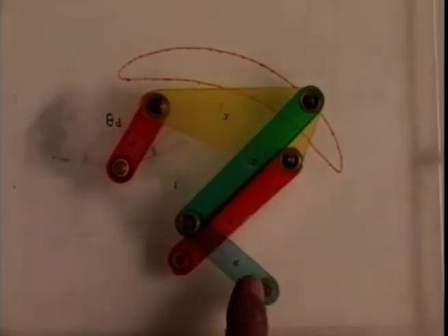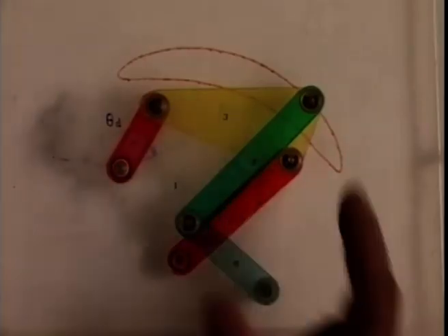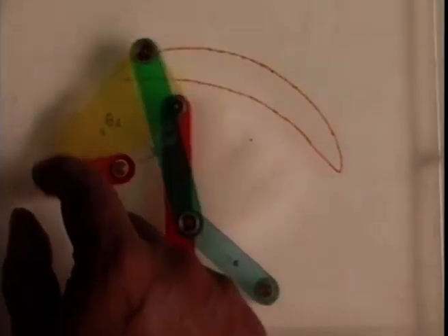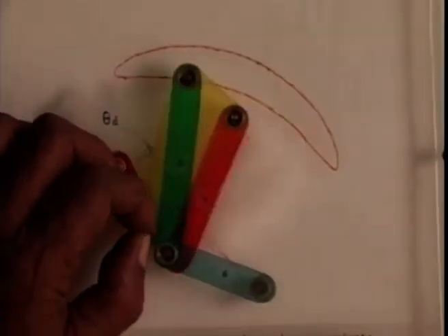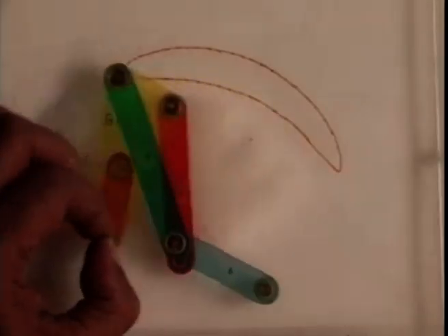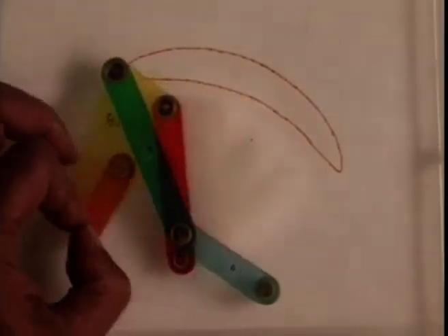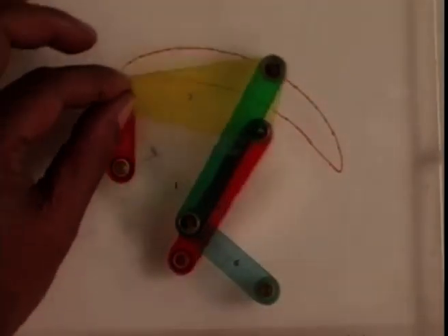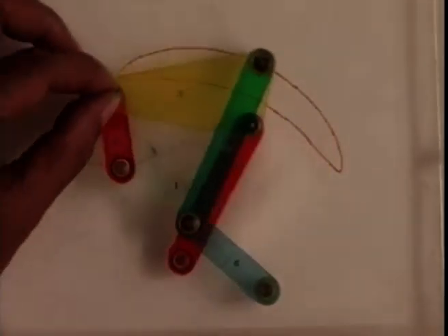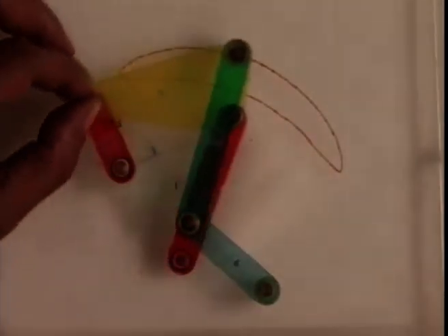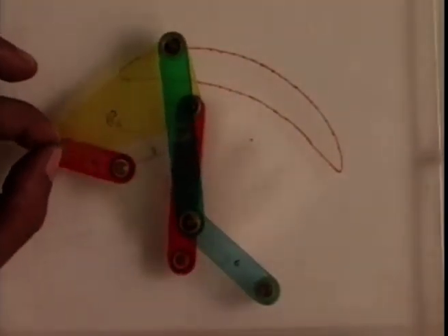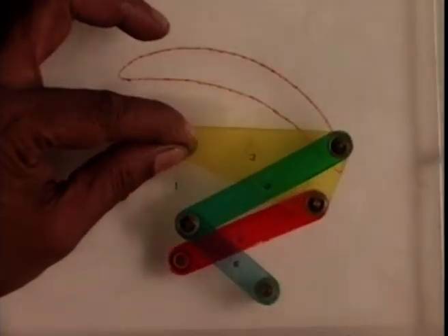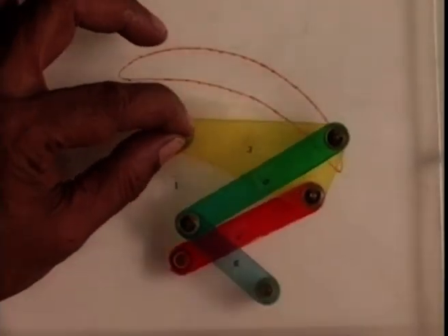So I can join another link here which I treat as my output link. As a result, we get a dwell mechanism such that the input link 2 rotates continuously, but as we see, the output link, that is link 6, undergoes two dwell periods. It moves, but for some rotation of link 2, there is no movement of link 6. For example, from here to there, link 2 is rotating, but as we observe, link 6 is not rotating,